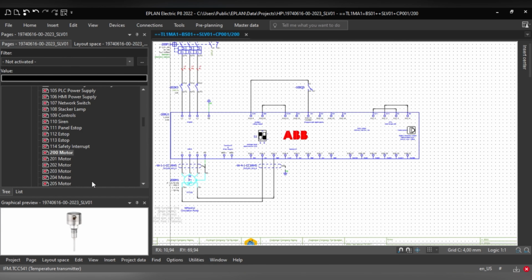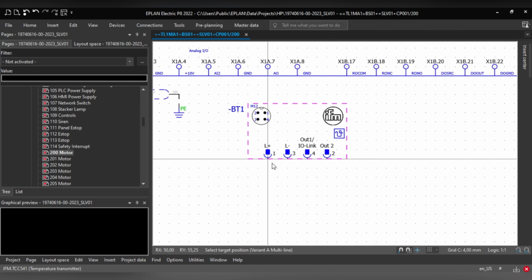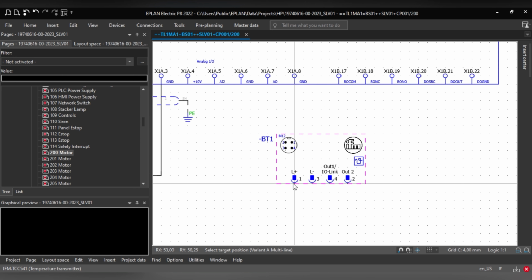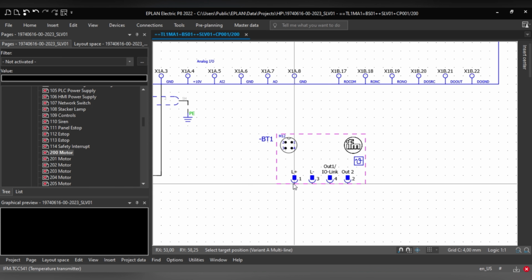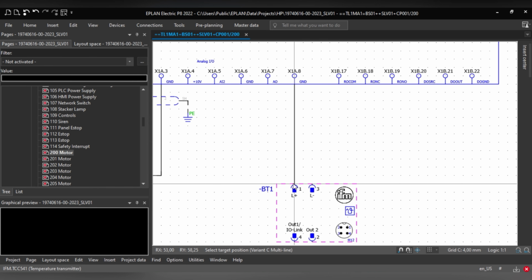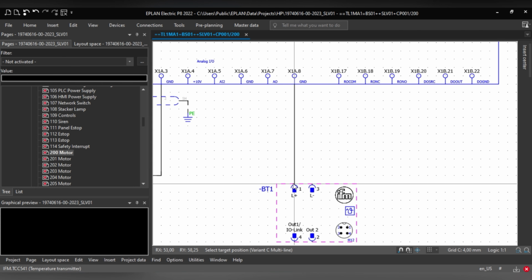Then you just click OK. Then yeah, there it is. It's included in your part selection. You can now use it. You can change the variants by clicking the tab button. You can change to whichever variant you want to use. So yeah, that's how you do it.